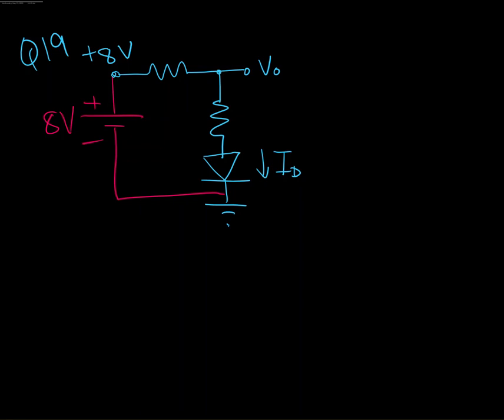So when we're thinking about this, we're going to need some resistor values. So let me add those in. I'll give this resistor a name, R1, and this one R2, just so I can write a formula. And so this is 1.2 kilo ohms for R1 and 4.7 kilo ohms for R2.